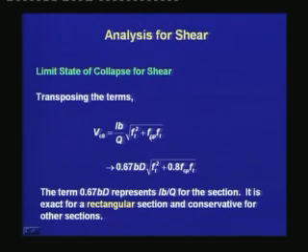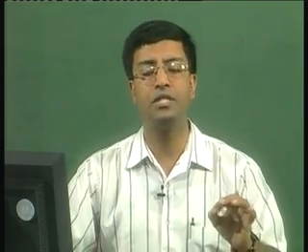Here we can note that if FCP is increased, that means if the prestressing force is increased, the shear corresponding to the initiation of web shear crack also increases. Thus, here we are utilizing the benefit of the prestressing force in increasing the shear capacity of the section.